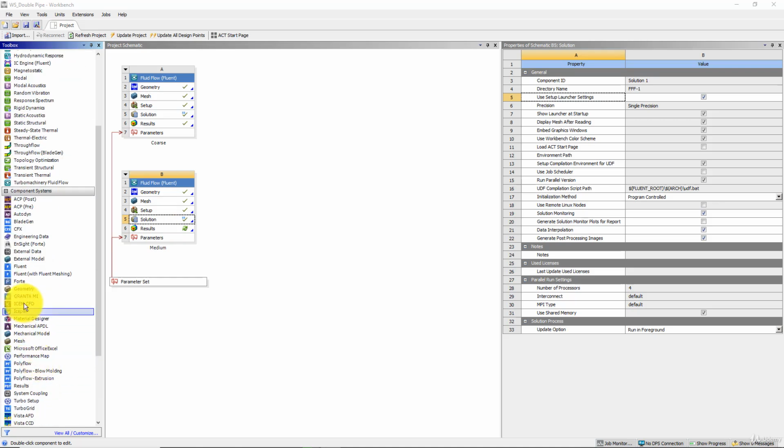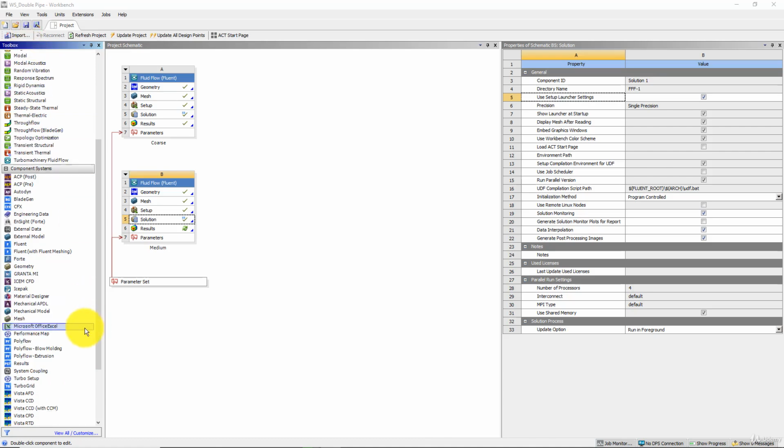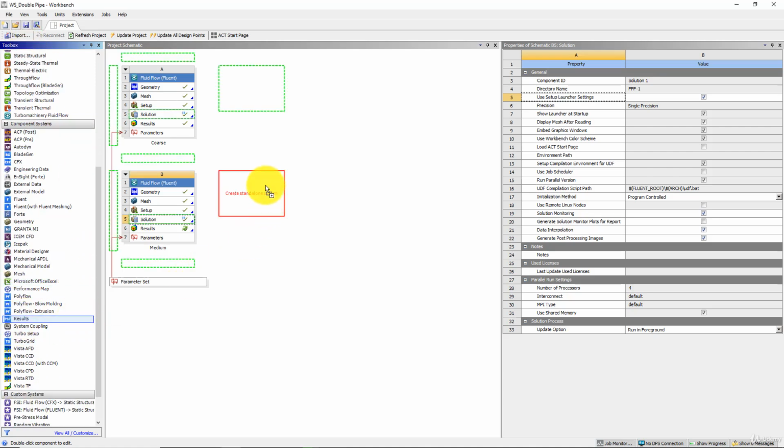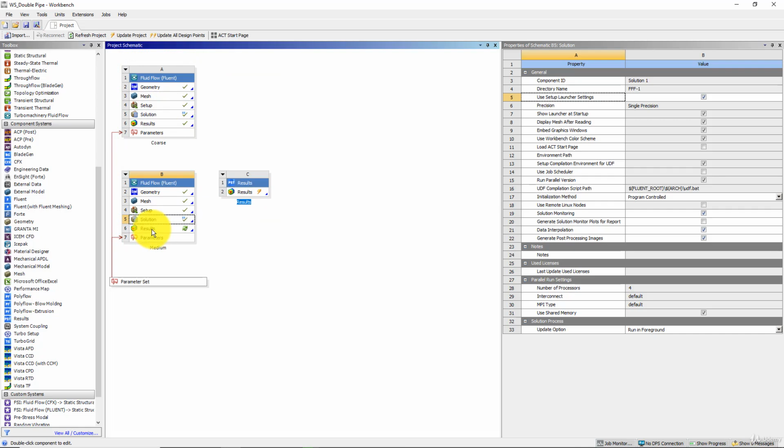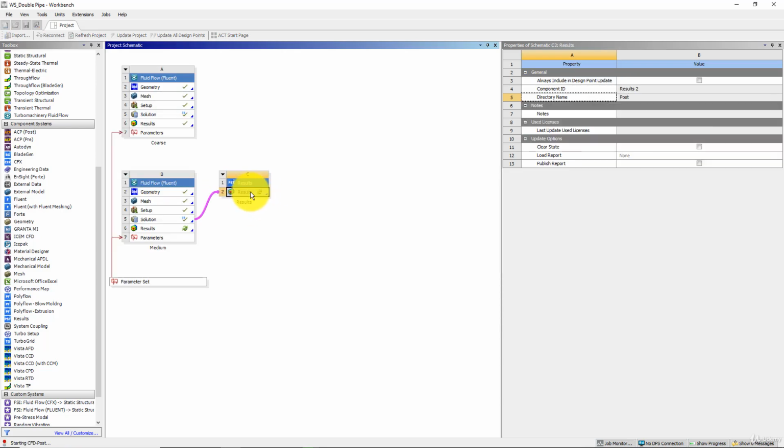You can take it from this toolbox, in the results part, the same as we can see in cells A6 and B6. If you want to analyze results in CFD Post inside Fluent, you can do it. If you don't want to, you can just click on the connection, put the data inside this cell C2, and double click here, and this will open CFD Post.